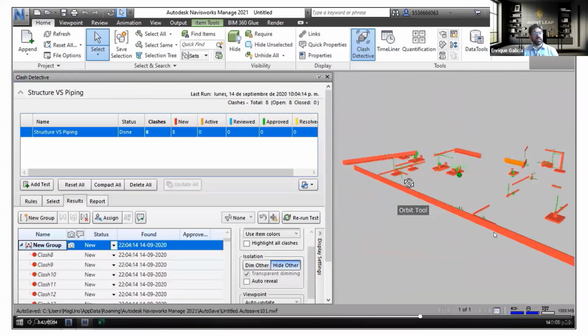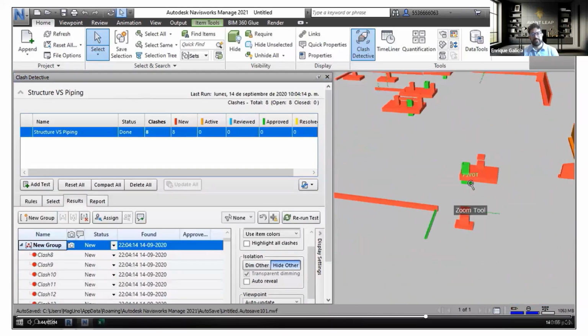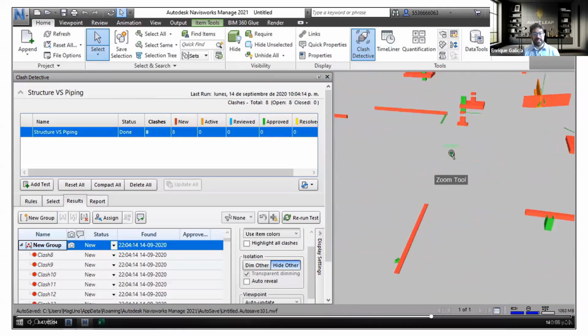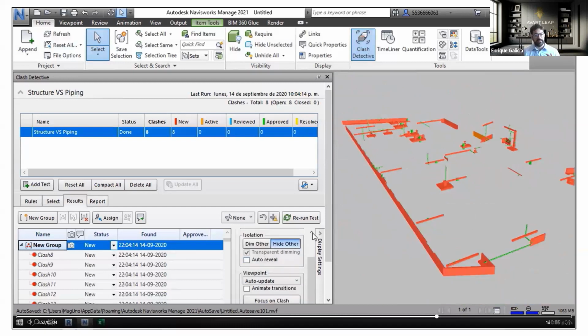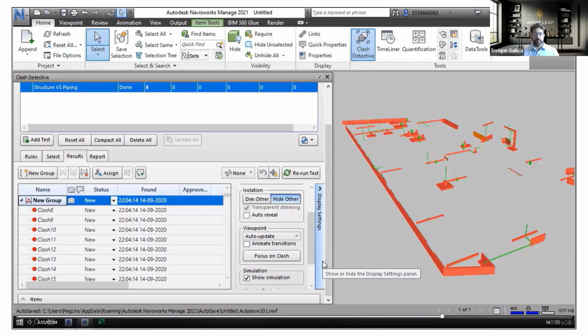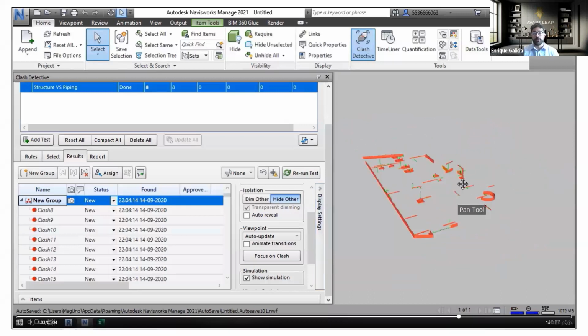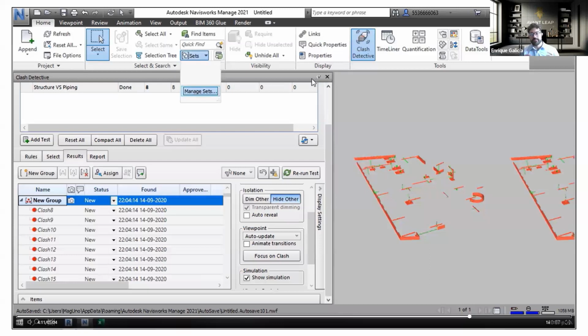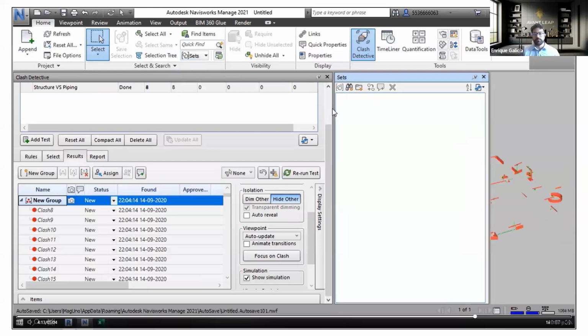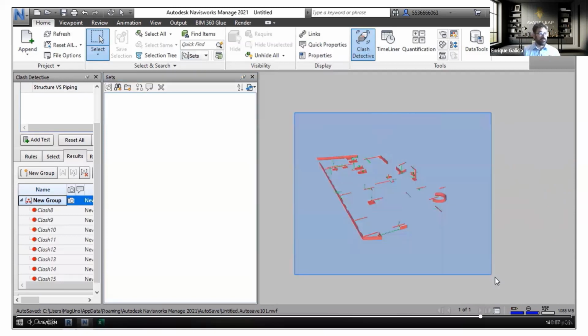Then once we have them, we will have a lot of clashes, because all objects that have an intersection will be found. That's when it becomes more complicated, because to review it we will need to have it on a board, in a meeting room, reviewing by priorities and finding the spots to be fixed. That might become very complicated because we need a leverage system or a priority. So what can be done from that perspective is getting an export, getting specific elements as visibility, exporting them back into Revit, reviewing those objects so that we know where the spots of intersection are, and then fixing everything around.